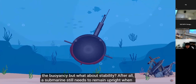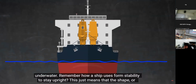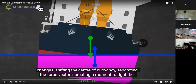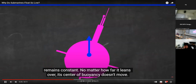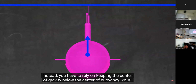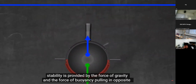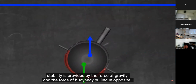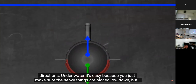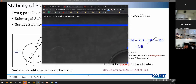After all, a submarine still needs to remain upright when underwater. Remember how a ship uses form stability to stay upright? This just means that the shape or form of the hull provides a righting moment. This is not how the submarine remains upright, since its centre of buoyancy doesn't move no matter how far it leans over. Instead, you have to rely on keeping the centre of gravity below the centre of buoyancy. Your stability is provided by the force of gravity and the force of buoyancy pulling in opposite directions. Underwater, it's easy because you just make sure the heavy things are placed low down, but on the surface it can be a little harder.